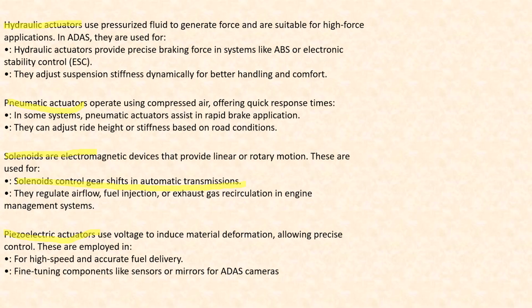Suddenly the vehicle is braked, and brake is applied onto the vehicle, then immediately at the low RPM, whatever the fuel is required, that precise amount of fuel must be injected into the combustion chamber. Okay, for such purpose piezoelectric actuators are used. Alright, even for fine tuning components like sensors and mirrors, as I mentioned here, piezoelectric actuators are used.